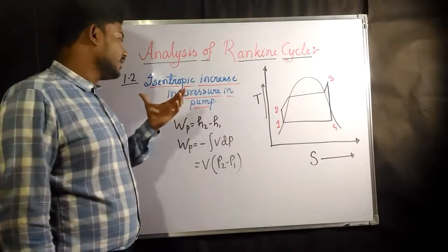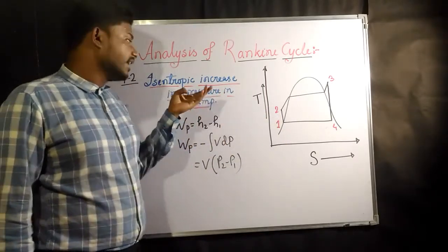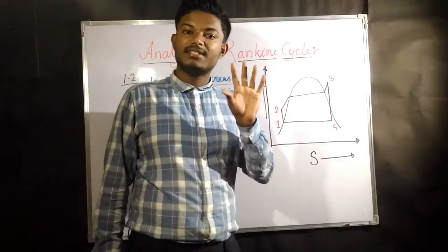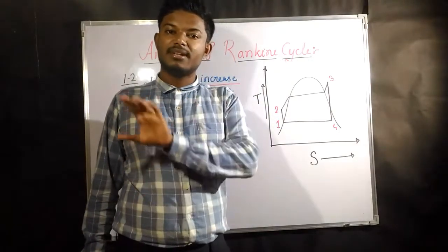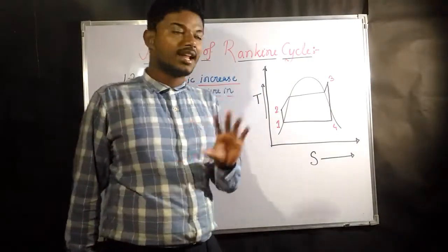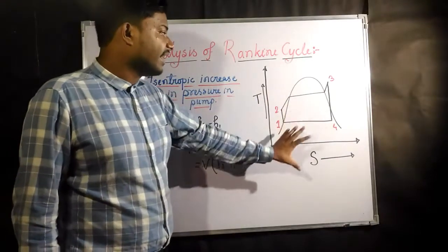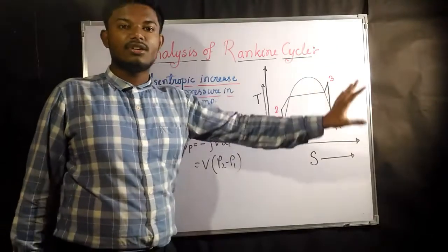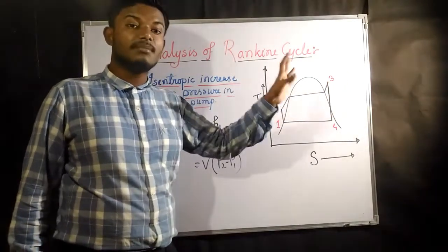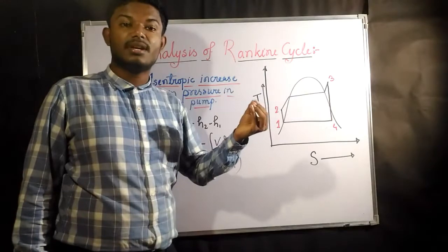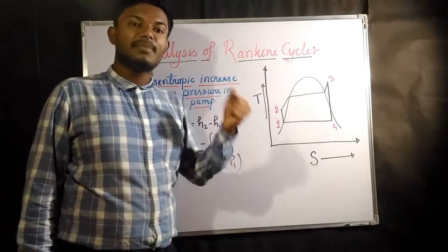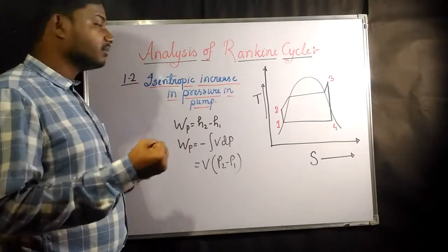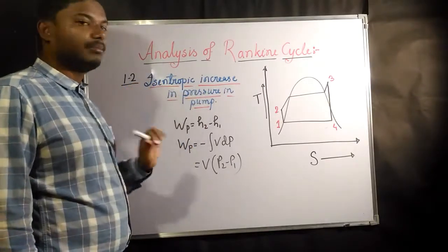That is adiabatic increase in pressure in the pump. Pump, or you can consider it as compressor. The same pump acts as a compressor in air standard cycle. Now here it is Rankine cycle, and the phases are changing all over the cycle. Somewhere it is steam, somewhere it is a mixture of steam and liquid, and somewhere it is completely liquid. So rather than telling it compression, we are telling that it is increasing pressure in pump.